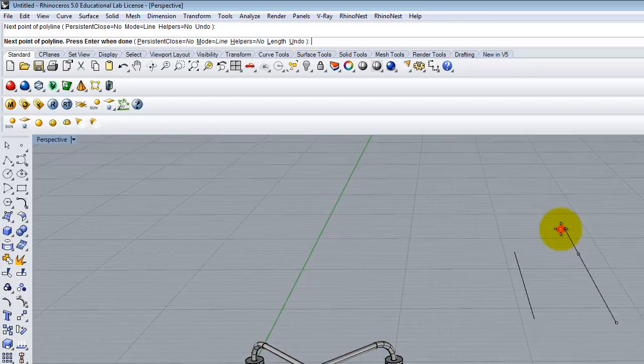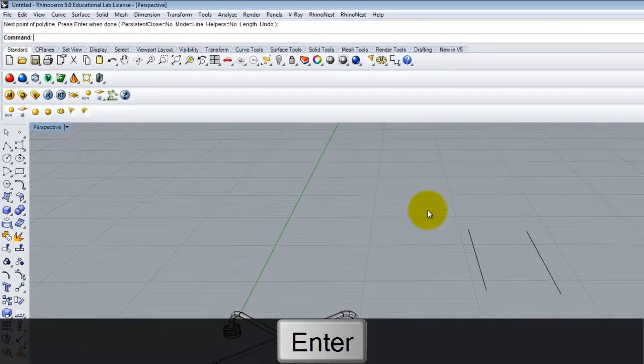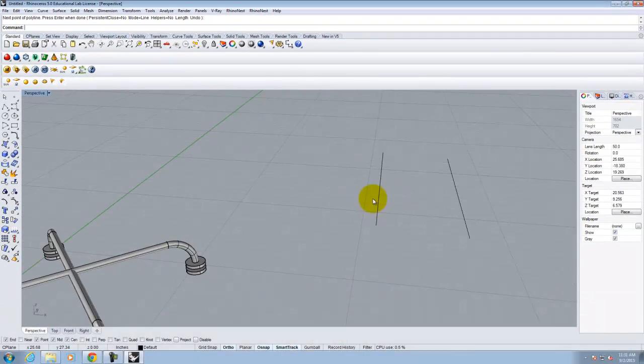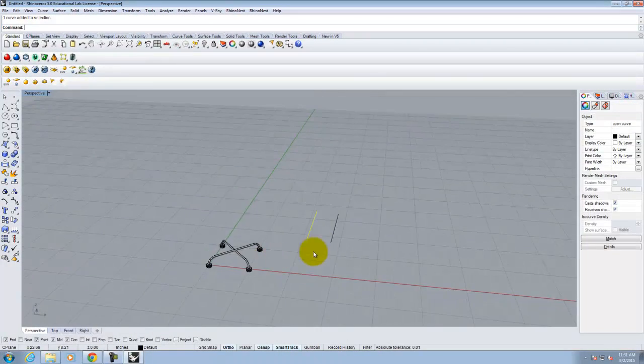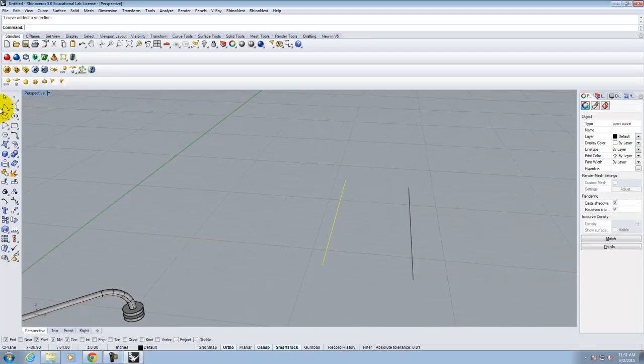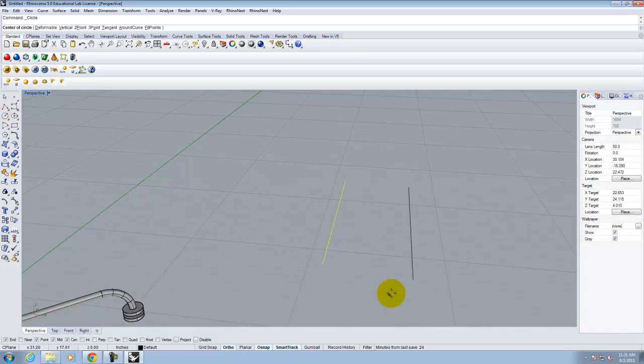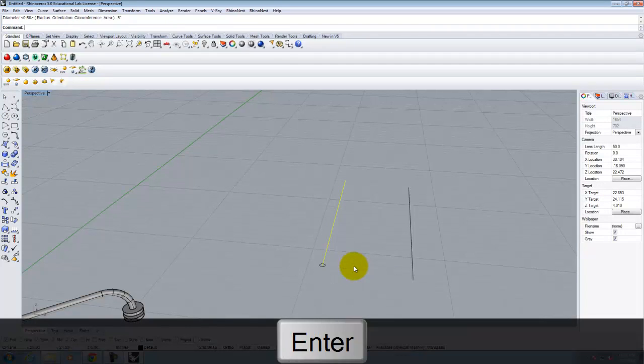Okay? So it doesn't matter which one of these I use, they're exactly the same. I'm going to work with this one. So the first thing that I need to do is to create that first sweep, that's the straight. So let me go ahead and go to my circle. It's going to be the same diameter as before. So I will say it's 0.5 inches in diameter.